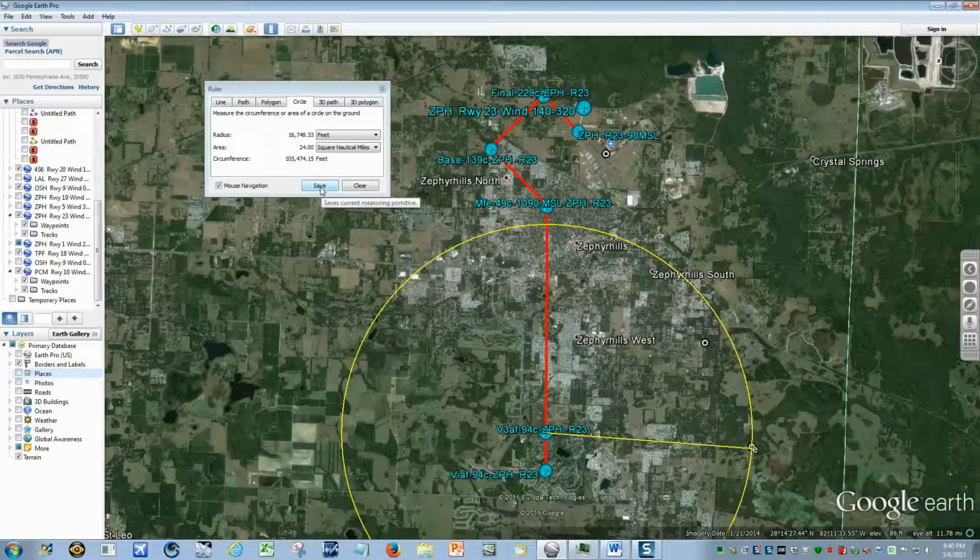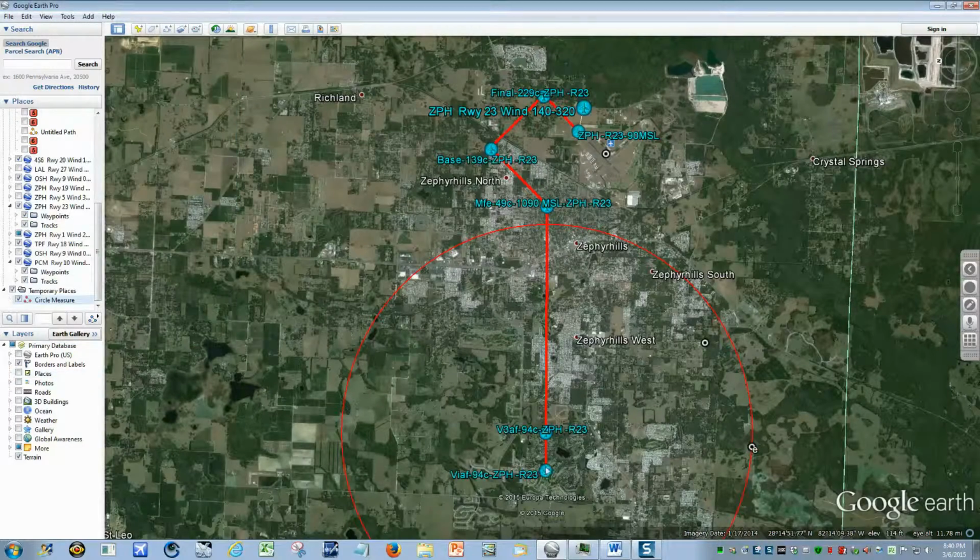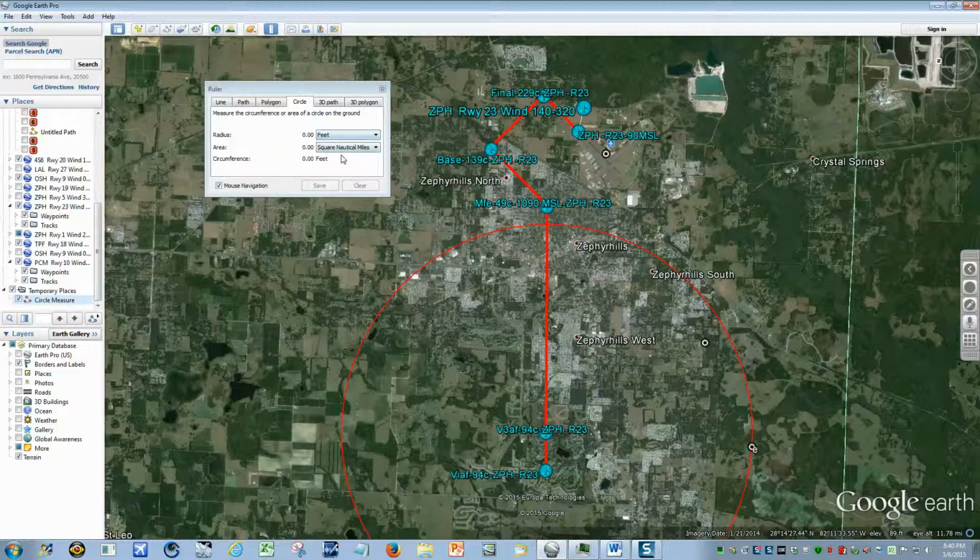Progressing along the approach path, the glide distance will decrease proportionally to altitude. Halfway along the path, at a 500 feet per minute descent rate, the altitude would be 1,590 feet MSL times 8 for the 8-to-1 glide ratio, which equates to 12,720 feet gliding distance. Redrawing the circle at the halfway point will identify additional emergency landing sites.